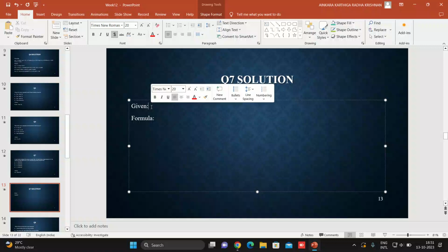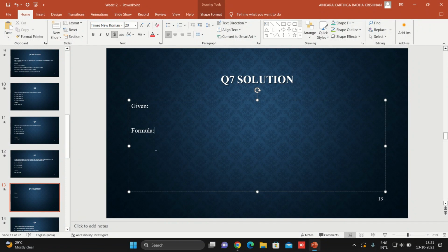So in the question, we'll write the formula first. Liquid holdup is given, so what is it? Liquid holdup is 0.72. So what is the gas holdup? It is 1 minus this. So 1 minus 0.72 is the gas holdup, which is nothing but 0.28.